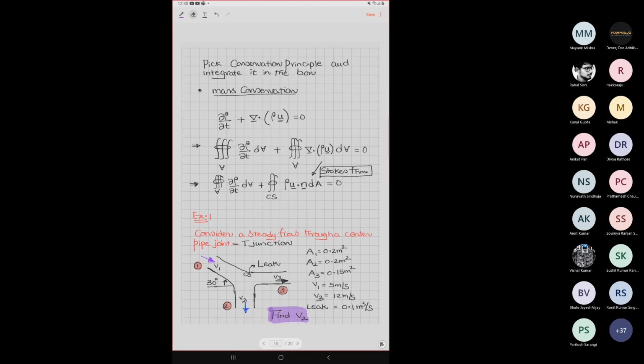Okay, so for that purpose, what I am trying to teach you is, because we have identified something like control volume, control surfaces, the mass conservation principle we have learned from previous classes is del rho by del t plus del dot rho u is equal to 0 for a given control volume. This is the thing I should apply. That means, though I have written it for an infinitesimal element, pile up such infinitesimal elements at each and every location, and add them up throughout that entire box.